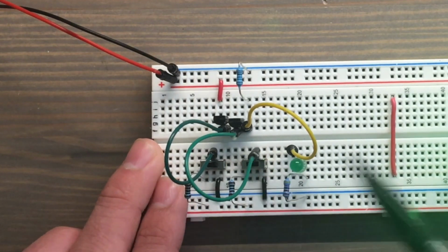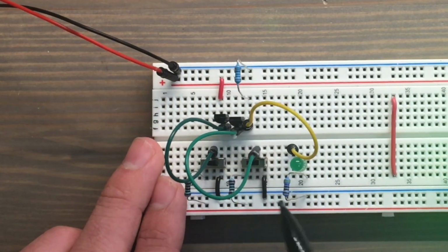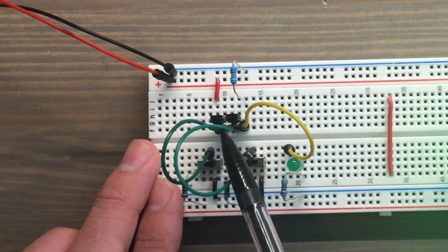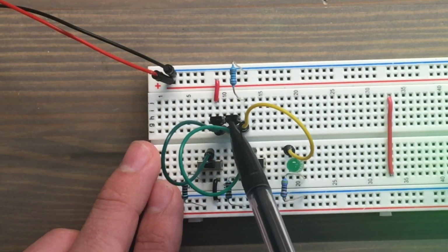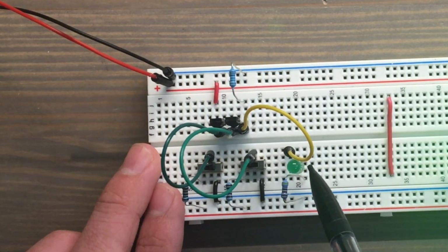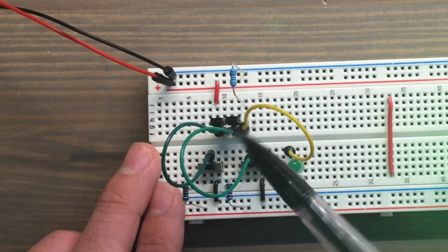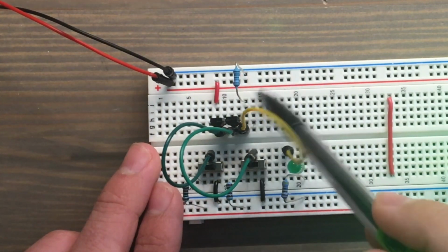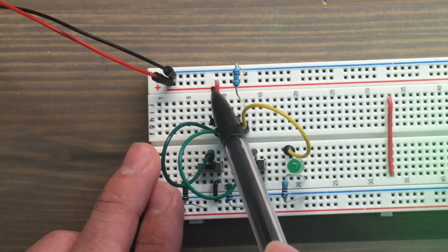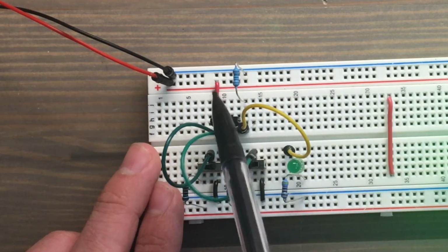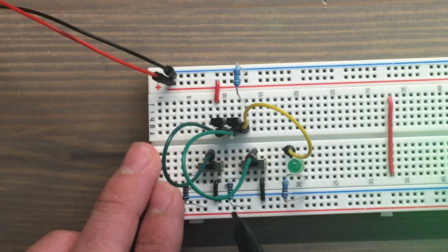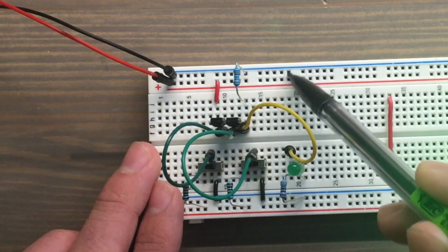And now you can see why I have resistors here. If I don't, when you turn this switch on, power can actually go from the base pin here through to the emitter pin here. But we have this to sink the current to ground when it has a resistor here. So when it's coming through this first transistor, it's the full 5 volts, but when we have a resistor here bringing it down, it can just be sunk to ground there.